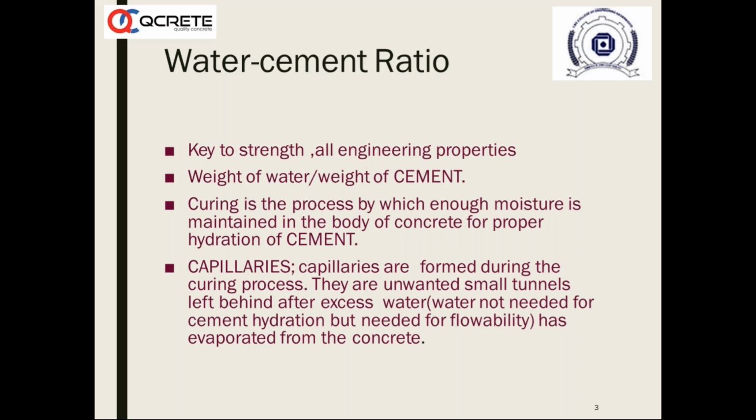Now, water cement ratio governs strength and all engineering properties of concrete, and we need to know another point. Curing is the process by which enough moisture is maintained in the body of concrete for proper hydration of cement. So, for example, you have done the concrete. You have to protect the concrete, keep the concrete cool in the initial stages and also continuously until 28 days, so that the water you have added be available for cement to undergo hydration.